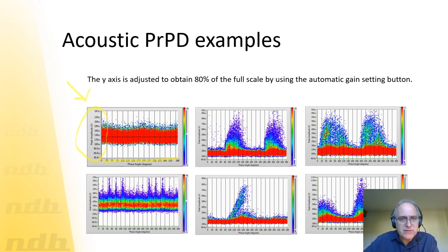So the same concept applies to bumpy, shapely waves over a cycle, and the waves or the type of shape will depend on the nature of the PD, but we won't get into it. So this is what we're looking for. Suspicious PRPDs. This is what we're looking for.